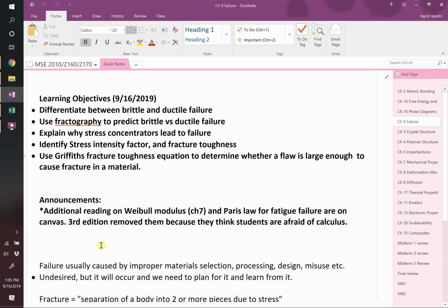We saw really heavily plastic deformed. And think of the things that we can change. We can change what? What can we change? Temperature, clearly, of the material. And what else? The stress is like the pressure, right? The amount of stress that you apply. What's that? Surface energy? The surface energy. These might be the same. Frozen versus not frozen definitely is a difference. Yeah. Like the point of breaking? Yeah. We introduced a flaw on the surface, which is the worst place to have a flaw.